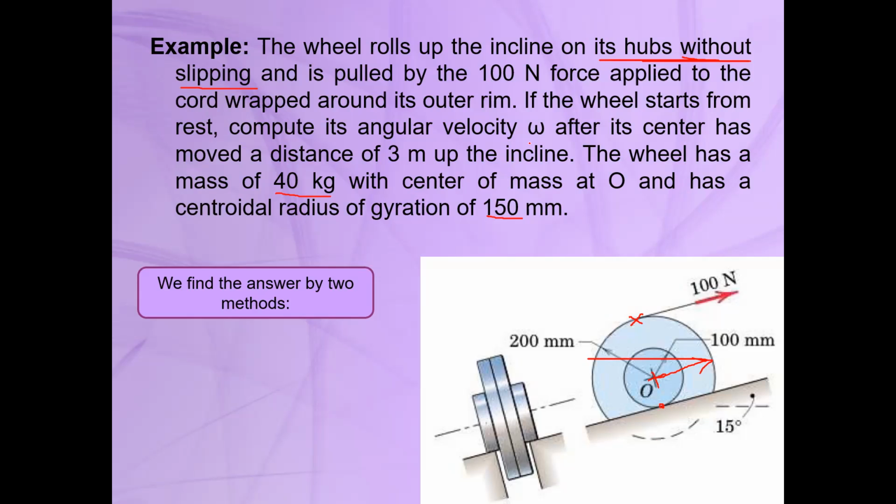Yesterday I mentioned when we have rotation without slipping. Exactly, thank you. Yes, we can assume that this wheel is rotating about this point, if we call it, for example, C, the contact point. We can assume that this wheel has a pure rotation about this point C, that this is a pin connection, and this wheel is rotating about this pin C.